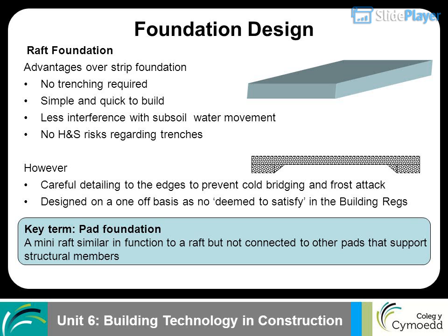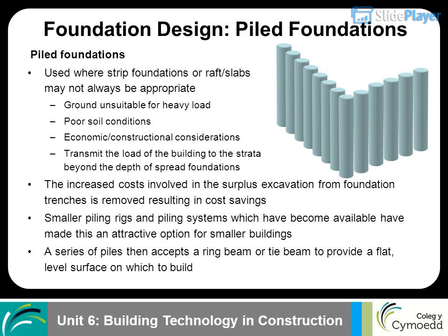Key term: pad foundation. A mini raft, similar in function to a raft but not connected to other pads, that supports structural members. Foundation design: piled foundations. Used where strip foundations or raft slabs may not always be appropriate. Ground unsuitable for heavy load. Poor soil conditions. Economic and constructional considerations. Transmit the load of the building to the strata beyond the depth of spread foundations.